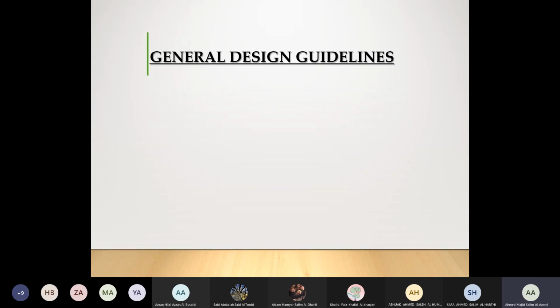First, there are certain general guidelines that we need to understand before entering the design of isolated foundations, and some of these have already been discussed roughly by Ms. Mazoon. It says the maximum bending moment occurs at the face of the column in a pad foundation.